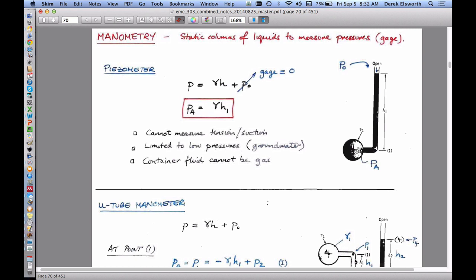So one example that's no different from the mercury case, but doesn't have vapor pressure involved, is what's often referred to as a piezometer, or you can think of it as a well. Exactly the same thing. If you want to calculate the pressure at the bottom of the Macondo well with a static fluid in it, or within the Macondo reservoir for that matter, where you're not going through the well, it's actually a very similar calculation.